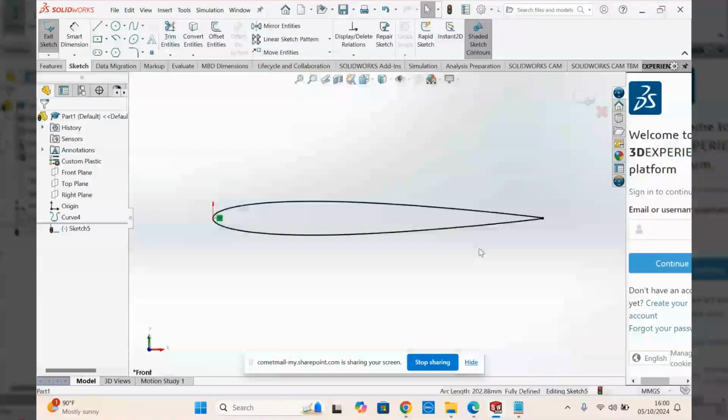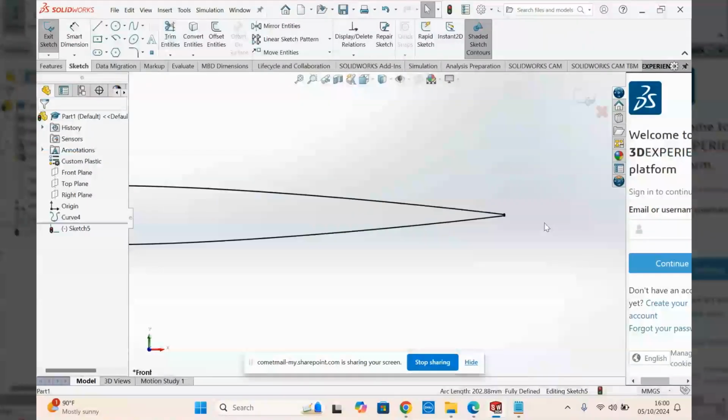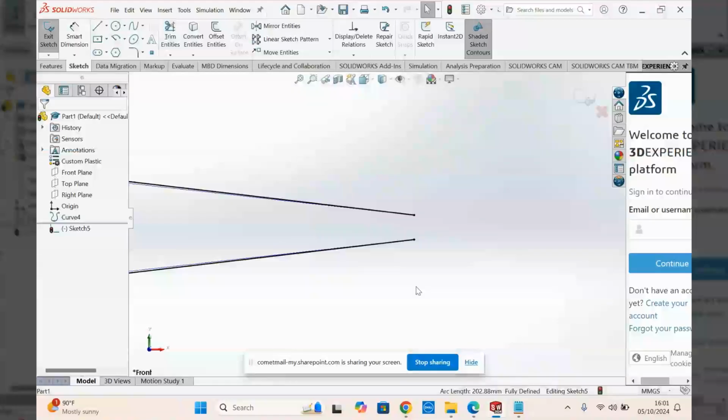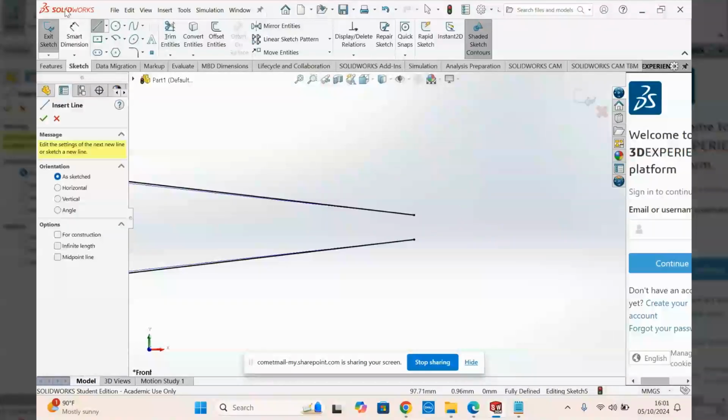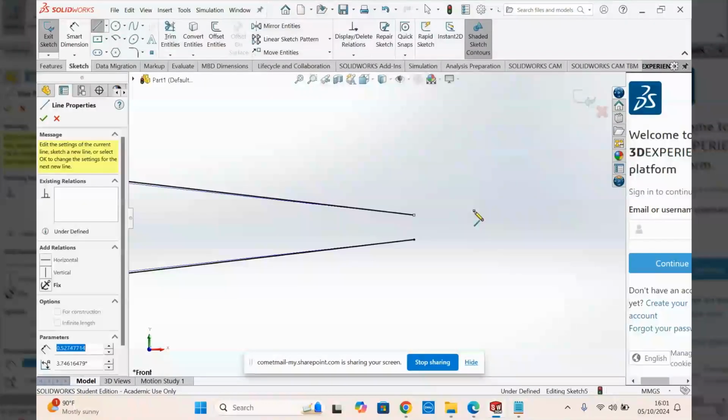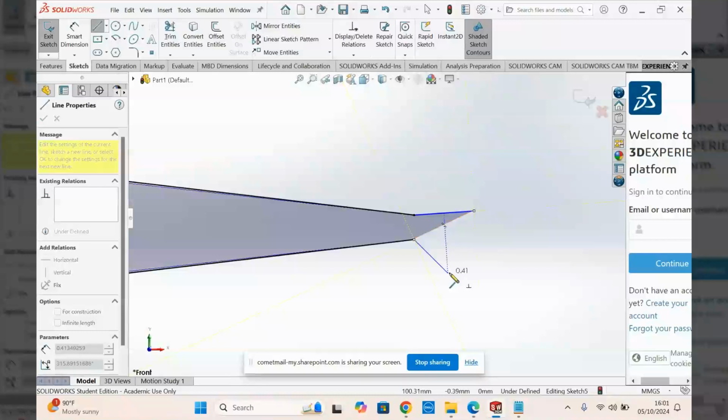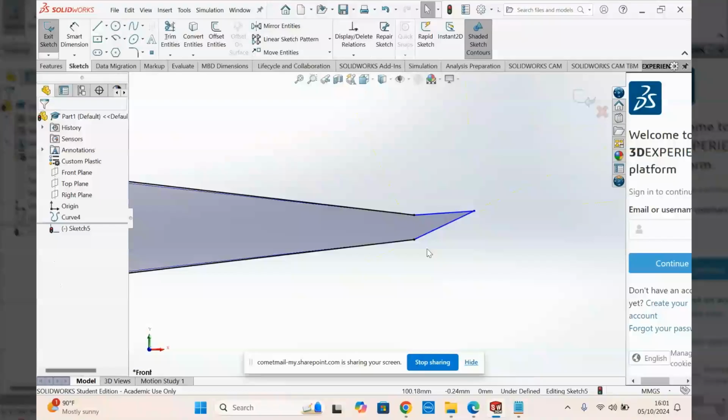But as you remember, we got rid of the first and the last data points, which means there's this little gap. So we need to manually put this back in. So you can do that. Click on the line tool up here, hover over so it's over this point, and just draw it arbitrarily. You're going to define these dimensions later, so draw it arbitrarily, and then you can hit escape, and that will close it off.